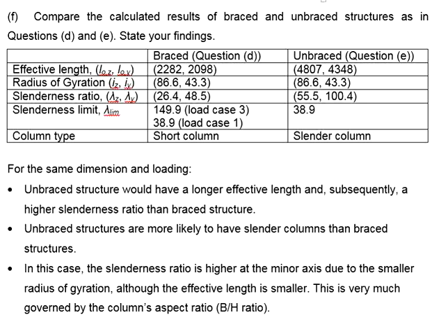Normally, engineers will prefer to have the short column instead of the slender column, so that they can do a quick checking in terms of their design by simply adding up the sectional area of the column, which ultimately will affect the radius of gyrations, or by simply deciding the type of the structure, whether it is braced and unbraced. Engineers can decide whether the column is going to be short or slender. Now you know the principles and know how it works for you to adjust the column, skew towards the category of short column, for simplicity in terms of the design. I guess this is the greatest benefit that you can learn from this example here.